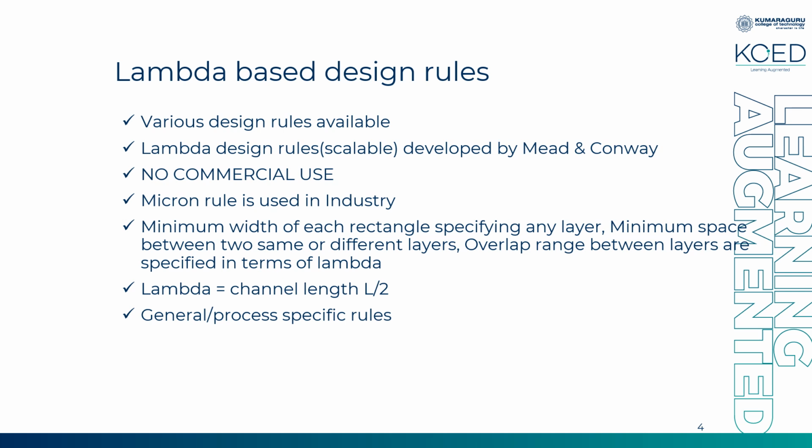Just like fabrication, for designing CMOS you had the N-well and P-well process, the twin-tub process. So here also you have process-based design rules. For a single CMOS to be fabricated, you had the N-well process, P-well process, SOI, twin-tub. Like this, here also you have a set of design rules that are process specific.